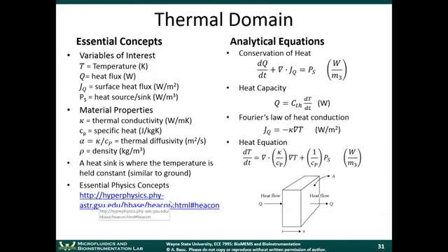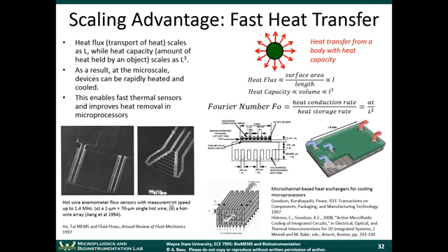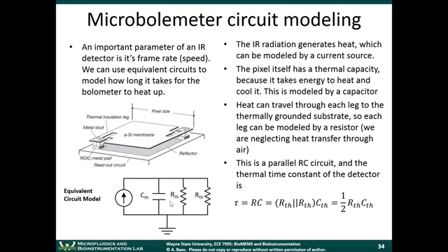In the thermal domain, we talked about circuits to model the thermal domain. Okay, in this case, you have a current source, which represents heat being generated in the system. If you recall with the microbolometer, you had a membrane, and when infrared light hits this membrane, it gets hot, so that's represented by this current source. And you have a thermal capacitance here and two thermal resistances here.